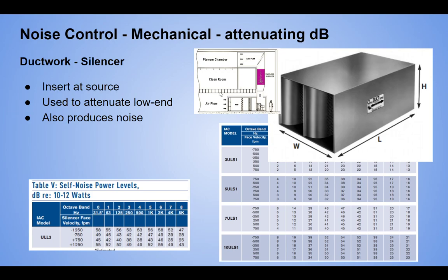You'll notice we've got some structure that isolates, right? We've got a lot of thick structure. This is why the sections are good to show this. So we've got an air handling unit, and then we've got structure above that isolates that. It's not close to it. And then we bring the duct up, put the diffuser as close to the mechanical equipment as we can get, and then we go out into the space.